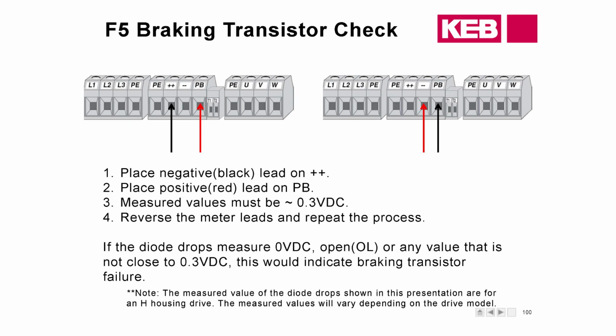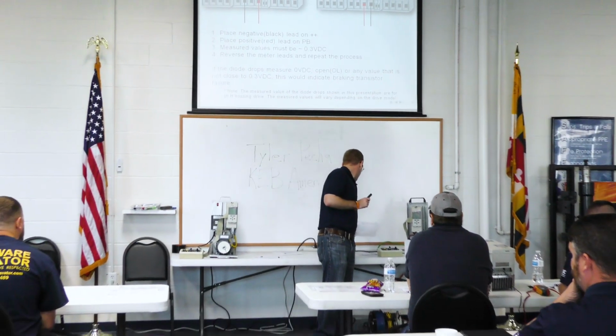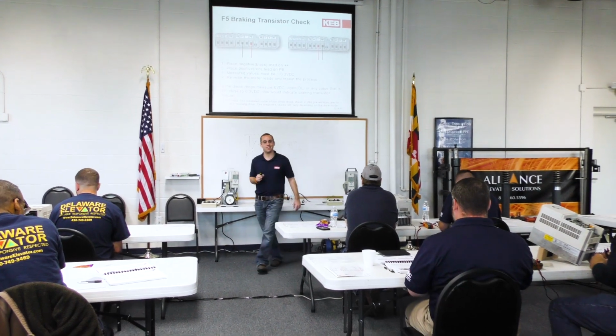So you're short there. What drive number do you have? 10. Yep, bad braking transistor.